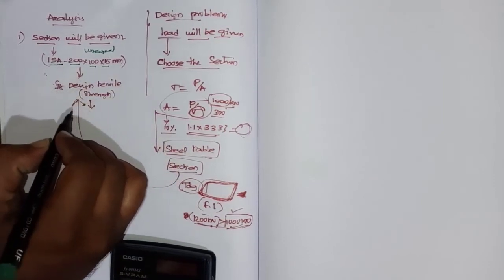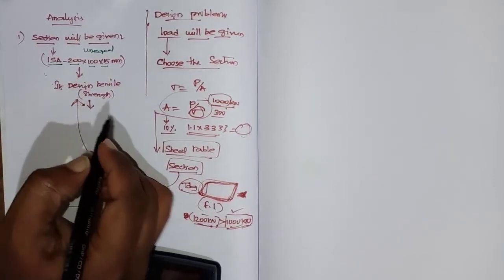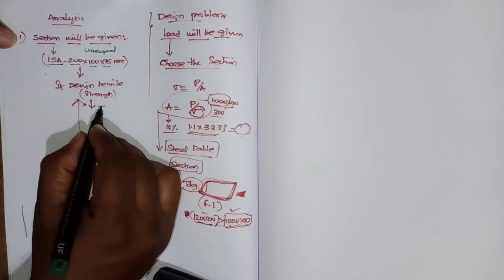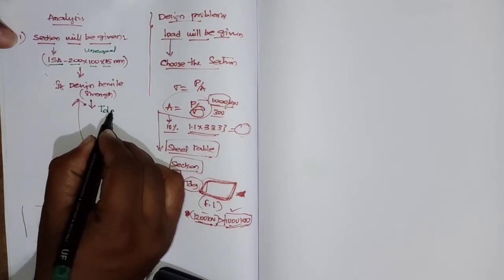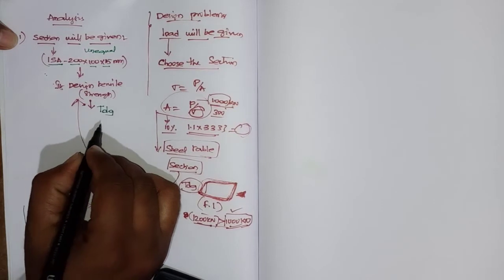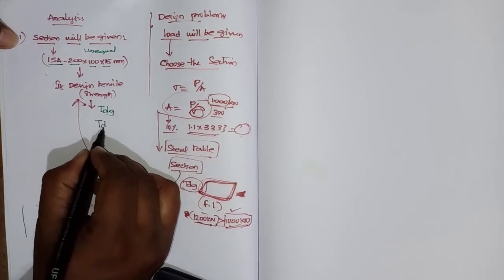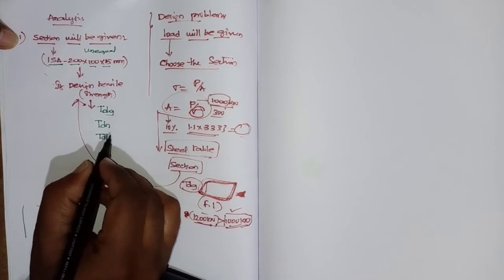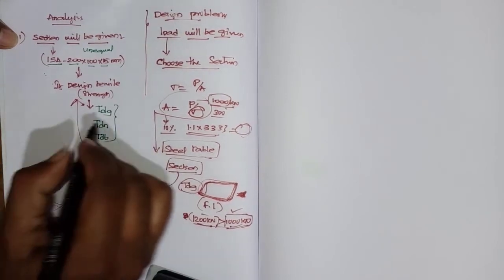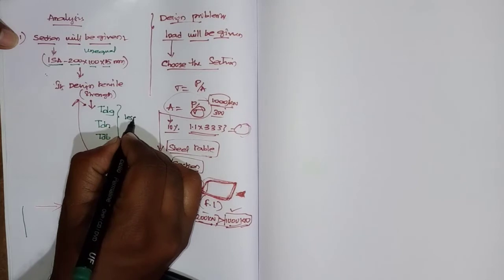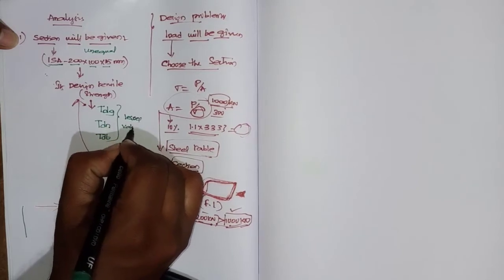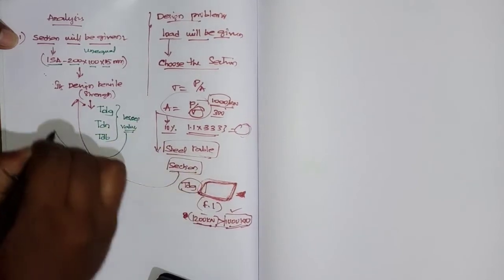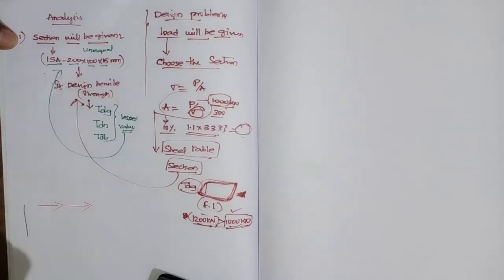You are supposed to calculate its strength. You will determine the design strength due to cross section yielding TDG, net section rupture TDN and block shear TDB. The lesser value of these 3 will be the design strength of this particular section.